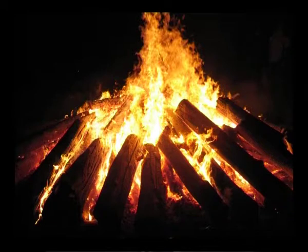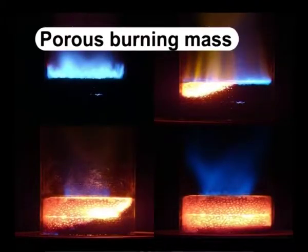In the absence of underfire air ports, air is admitted along the sides or from the top of the furnace, and combustion proceeds in the same surface burning manner as in the bonfire, but with improved conditions due to the re-radiation of the heat from the surrounding furnace walls and roof. Unless the refuse being processed provides a porous burning mass, it is necessary to provide manual stoking with slice bars to stir the mass of refuse in order to achieve a reasonable burning rate and degree of burnout.